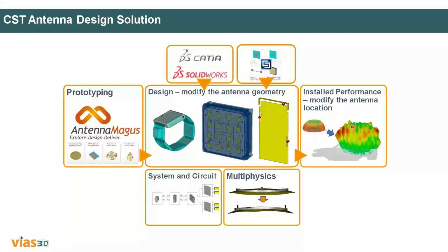They will create a lot of noise, or some problems, some gain distortion towards particular angles, which is not acceptable. It's always preferred to understand the coupling interferences if you're placing an antenna over a geometry. So if you are designing something for industry, you import a geometry, place the antenna over it, and then do the simulation.